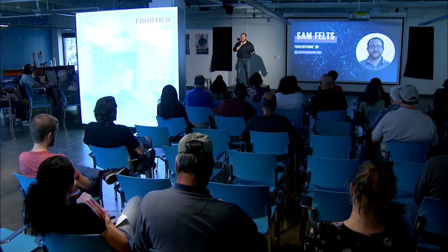Yeah, so I'm actually going through this right now. I had a discussion with a designer today on why we're not going to use glue. We try really hard not to use glue. OSHA doesn't like glue. But yes, we do often, especially if we're doing things like instrumentation or surgical simulators, we'll include extra parts, and in the same way we made those assembly instructions for the manufacturer, we'll make similar IKEA-like guides for technicians or for the customer to swap out those specific parts. Because sometimes you know where your failure points are going to be, and it's anticipated, the customer knows it, here's how you swap those.